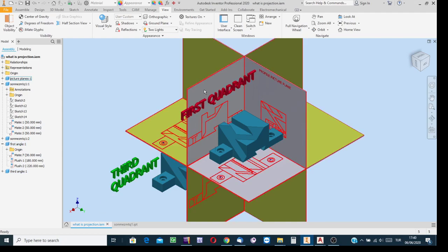Between the frontal picture plane and the horizontal picture plane, along the folding line we have the x-axis of the Cartesian coordinate system. Between the frontal picture plane and the profile picture plane, we have the altitude axis, the z-axis, and between the horizontal and profile picture planes, considered as coinciding with the folding line between the picture planes, the y-axis.